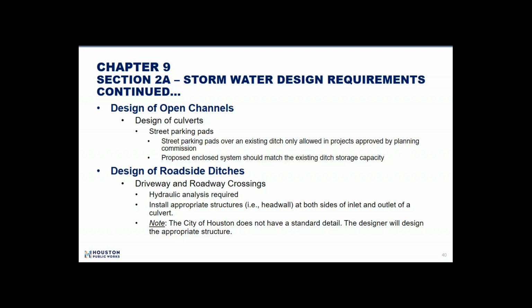And then, in the past, someone would just throw in a culvert with no attention to the edges. You can't go down a roadway or highway without some sort of head wall structure on a highway culvert, some sort of inlet protection. We need to take a somewhat similar approach, though we're not dealing with the speed of highway traffic, but we're going to start requiring, or have been requiring, head walls.